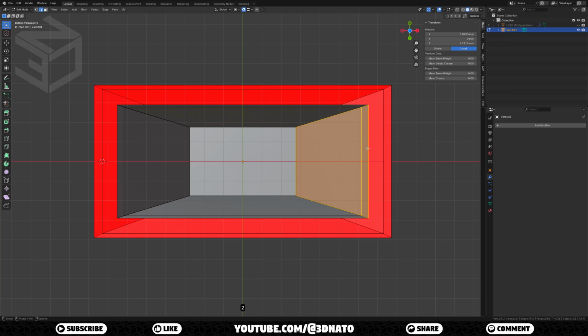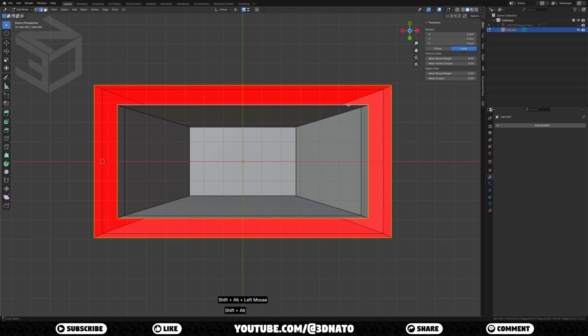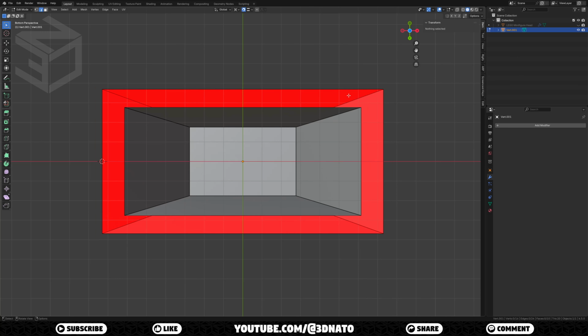Enable Edge Selection, select this edge loop, and on the Transform panel, set the Z location to 1 mm. Now let's round some edges, but before that, let's delete these two bottom edge loops. We'll extrude them back after the bevel. Select both edge loops, press X to delete, and select Vertices. Now press Shift+Tab to disable Snap.